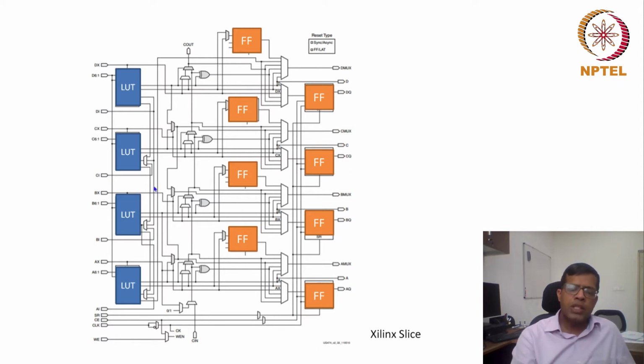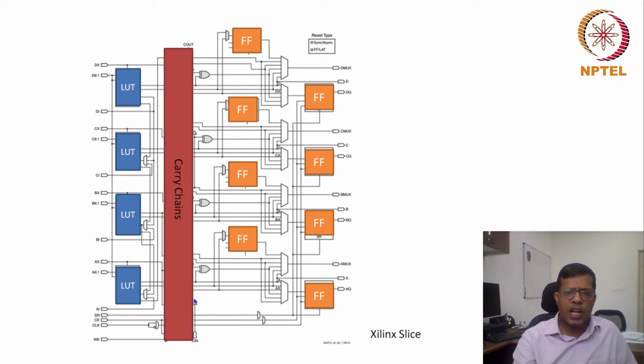Further, as we have pointed out earlier, addition is quite a popular circuit, but we never know what size of addition we require. That is why there is an internal carry chain circuit. You see Cin is given as an input, and the output generated by this LUT is also given as a carry into the second.